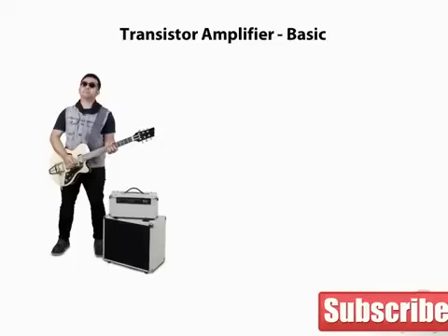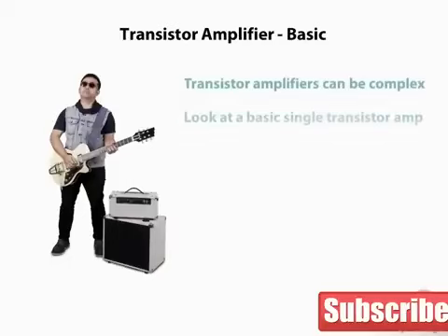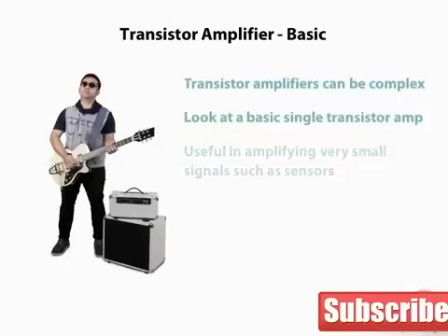I know what you're thinking. No, this is not me playing my favorite pop tune, but it does show us an example of a practical application of an amplifier. The guitar amp is a very complex amplifier, composed of many stages of amplification and other circuitry. The initial stage would be to amplify the very small signal from the guitar pickup to levels that the later power amplification stages can use.